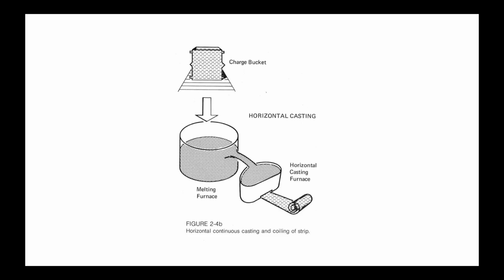By using horizontal casting, in many cases, the thickness can be minimized on a material, say on a strip here, so subsequent processing can be cut down if you're casting and rolling. This has been used successfully in a number of facilities and was the first usage for this type of casting. But also, like I said, horizontal casting is used on alloys that need a longer time for freezing or solidification. Very important.